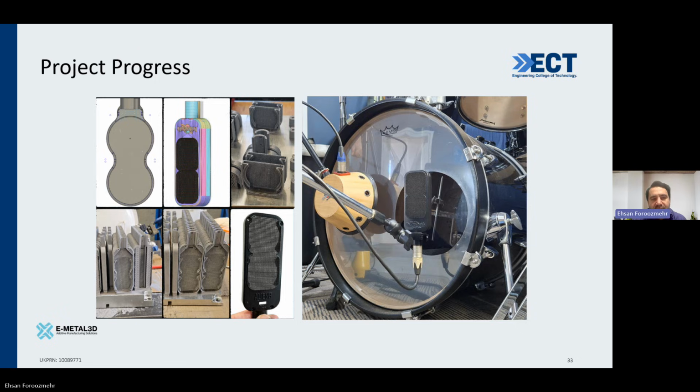Then we tried many experiments to find the best parameters for the mesh structure and so on. Everything was tested. Once happy with that, we tried changing even the support to minimize the print time, and that has been one of the batches of print. In each print, we are able to print 39 cases of microphone, which is basically 78 parts. And the final design is painted black. And this is what you can see.